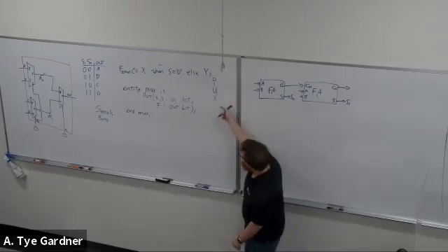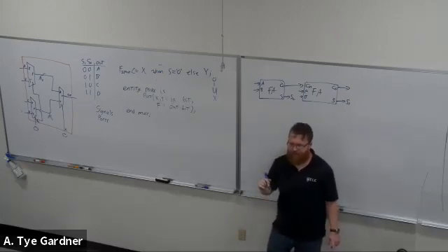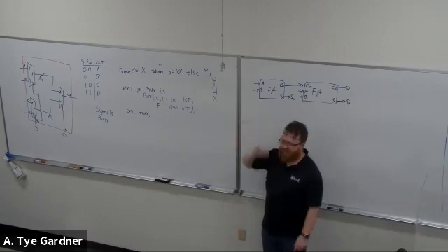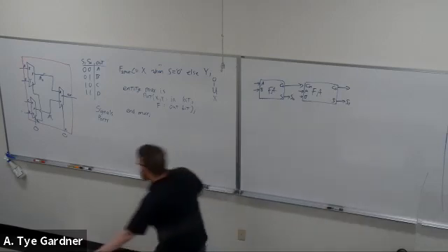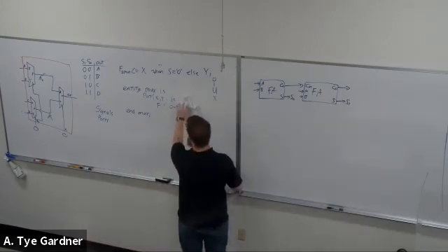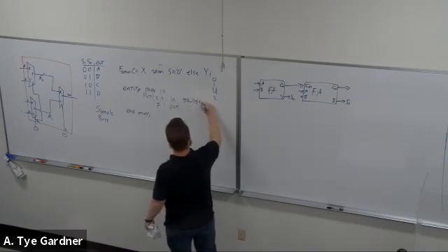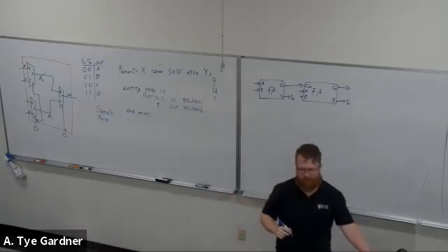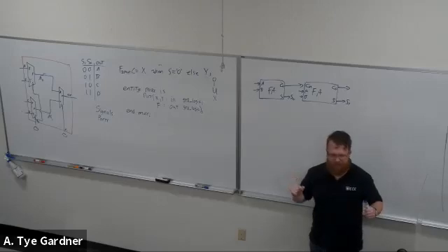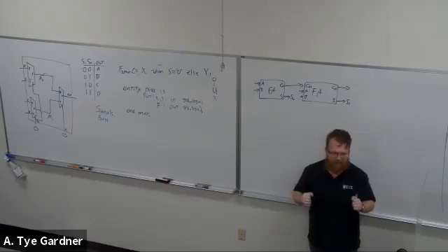There are 3 or 5, I forget, other values that this can be that we will get into later. My point is we don't necessarily want a bit because a bit is a poor reflection of the real world, okay? So what we do, instead of telling it bits, I say they are standard logic. Okay, standard logic is basically just a bit, but it can have all of the values that the real world can throw at it. It is a better representation of the real world.